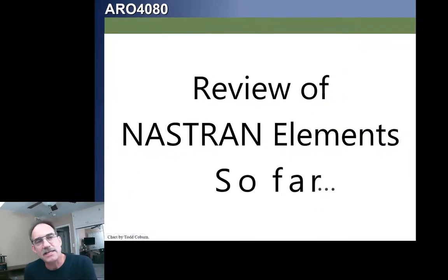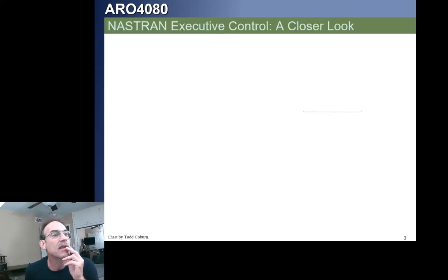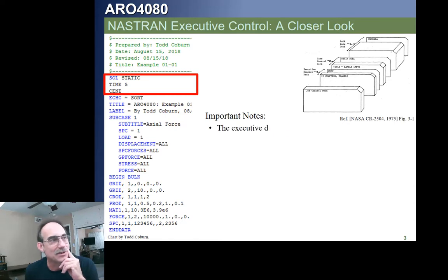Let's see how. First, let's take a real fast look at what we've already learned about NASTRAN elements from Lecture 1. We learned about the NASTRAN deck. We saw that comments started with a $ sign, and that it's good practice to put your name and the date and things like that up there at the start of your deck. You also can use commands within the deck to report this, to solve this, to store this kind of information, but it's good to do it both places so you see it right at the start of